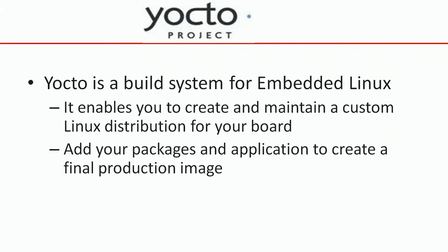So we can build up a layer which defines the Linux kernel, add another layer which defines your board support package, another layer that defines the applications that you want to add to it as well. Then when we build it, the Yocto system will download all of the packages that we need off the internet and then build our final Linux system. It's absolutely fabulous, and it really does start to work extremely well.